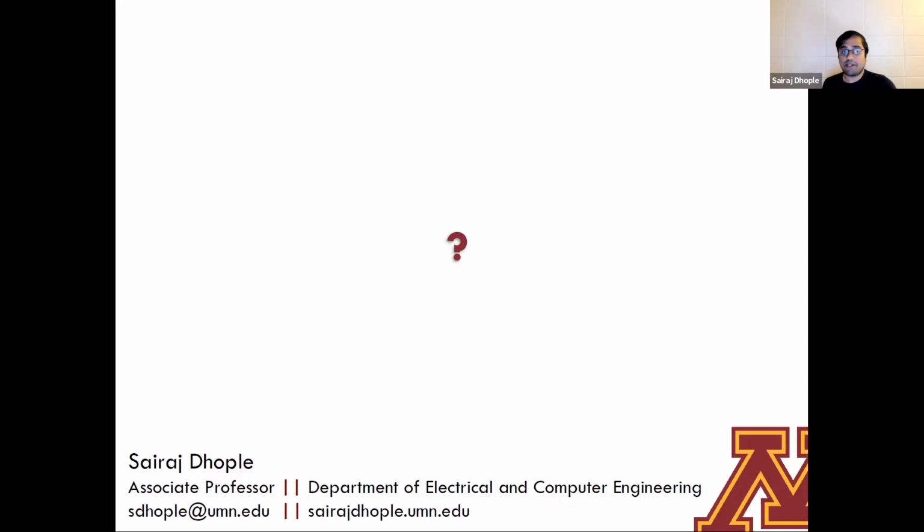But if you want to write down differential equations and you want to know what happens on faster timescales, or you want to prove that, hey, look, you're going to get to these sinusoidal steady states, that's very difficult, if not impossible, to do with phasor domain methods such as droop. That's what I meant.